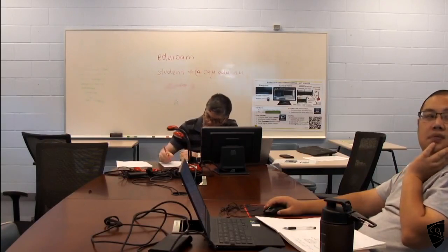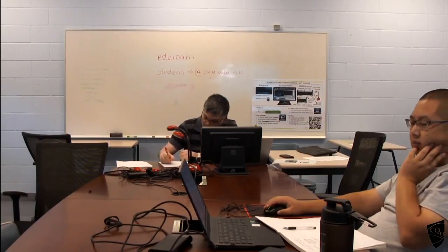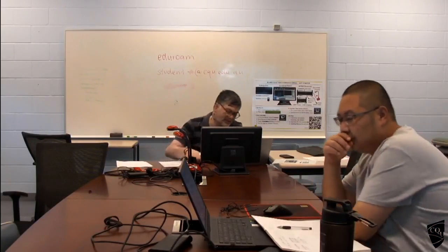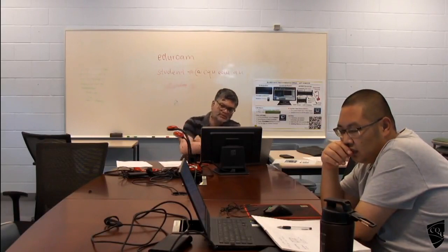So Lx and Ly. So what is a one-way slab? This is called a two-way slab. One-way and two-way slabs are named based on the load transfer mechanism. If the loads are transferred in both directions, it's a two-way slab.